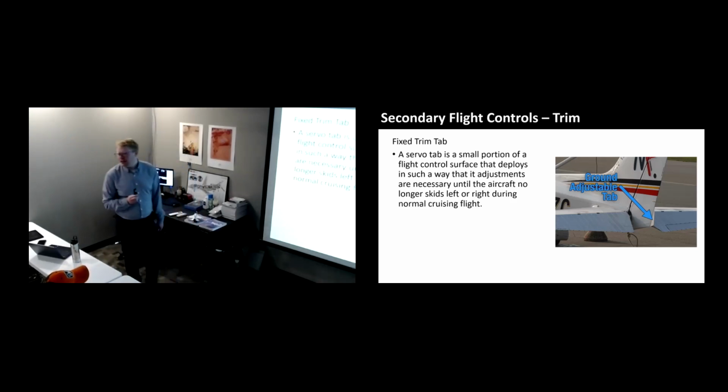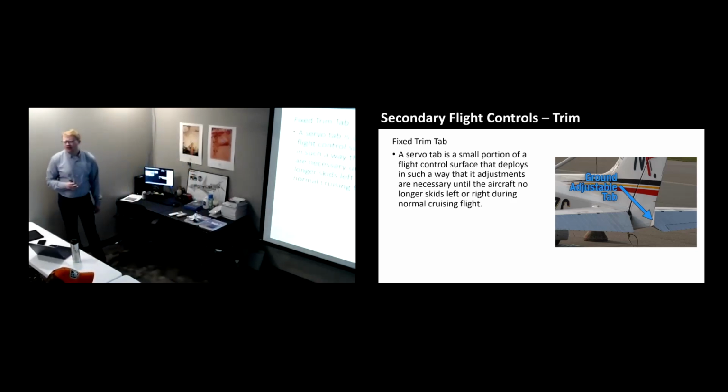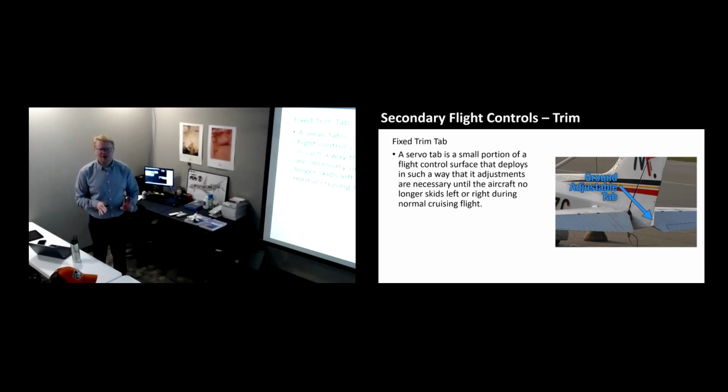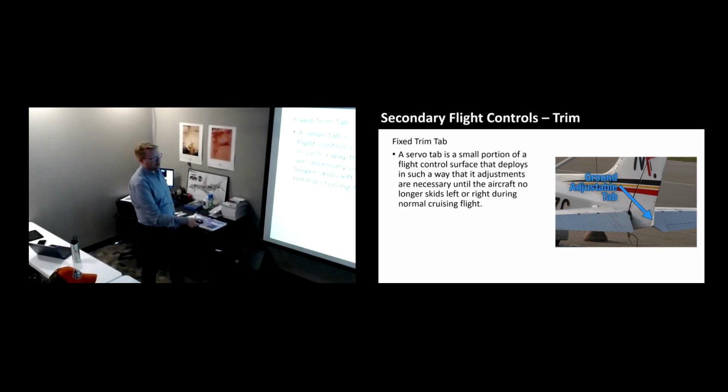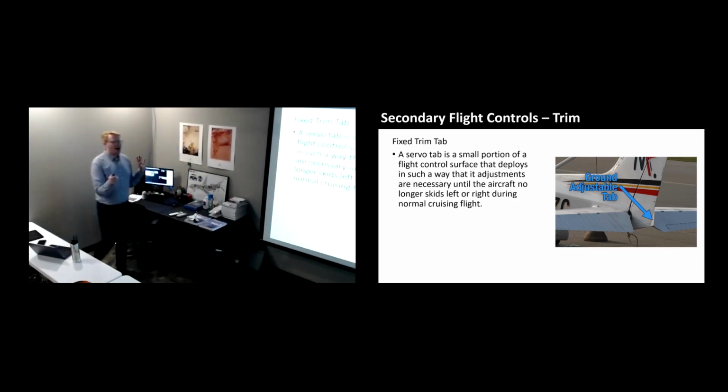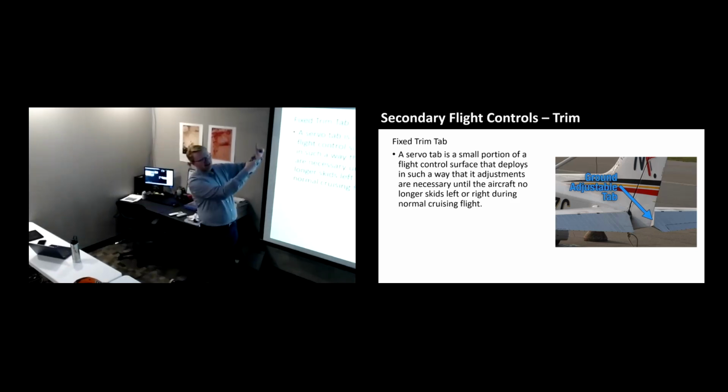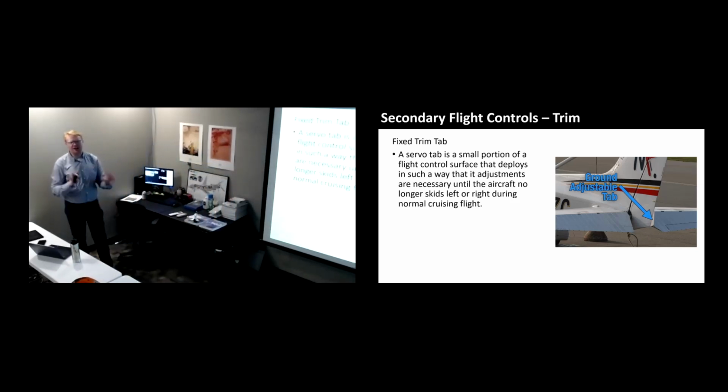I got to fly maybe 2.5 years ago on a special permit to fly an airplane. We had an issue where pilots were saying, yeah, I never need right rudder. I feel like I need left rudder all the time, and I should need right. Something seems off. Turns out this adjustable trim tab was out of balance. So maintenance put it back. I went to fly it, it's totally fine. But believe it or not, this tiny little piece, it's only like this big, makes that big of a difference aerodynamically.